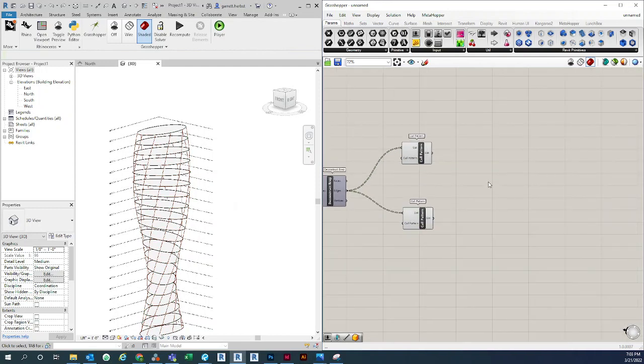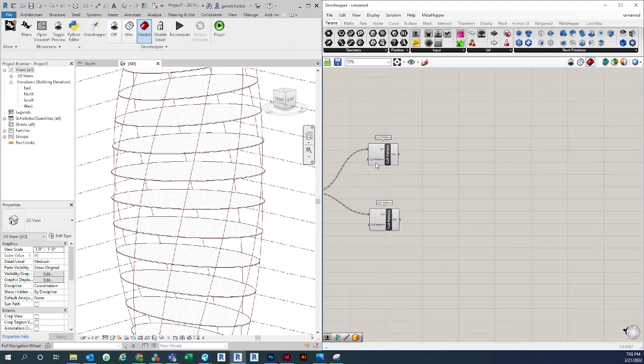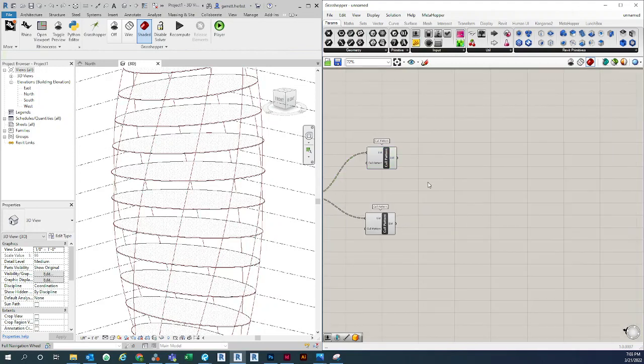One thing we need to be cognizant of is that even though these look relatively straight between the 2 points, these are actually curves. All these edges are technically curved, and Revit columns and beams work off of perfectly straight lines, or axes as they call it.